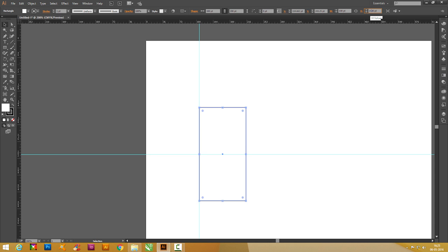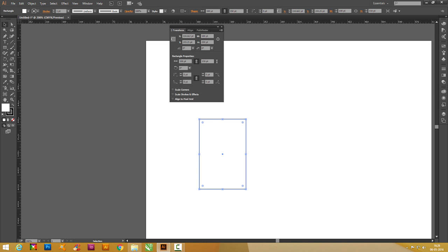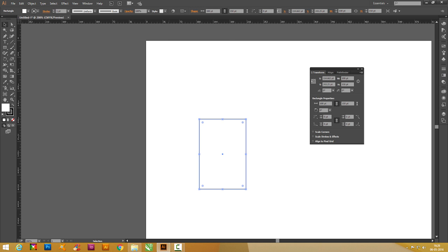And now next, when you select an object, here in the Window menu you have got an option called Transform. So what is the use of Transform? In Transform again we get the same X, Y, W, H options and the reference point options, and along with that I have got two more options called Rotate and Shear. So using Rotate, I'll be able to specify a particular value, and my object will start getting rotated about that.